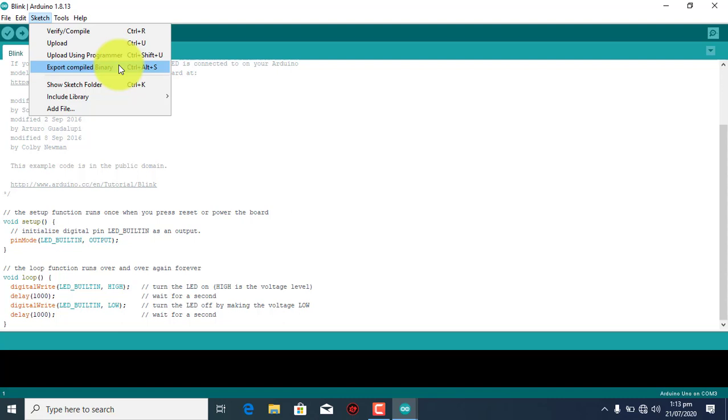What this will do is that it will compile your code and convert it to hexadecimal value. So what you just have to do is plug in the programmer that you got. Like me, I have a universal programmer which I use. So what I just do is select the hex file, put my chip in the programmer, and send the hex file direct to the chip, and it will work just fine, the same as programming direct using upload with Arduino Uno. So if you don't have Arduino Uno, you can always generate the hex code and then send it direct to your microcontroller.